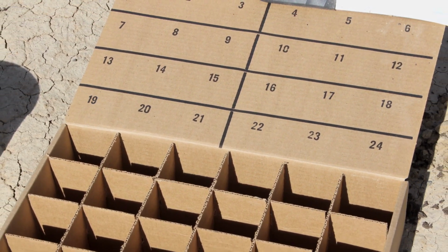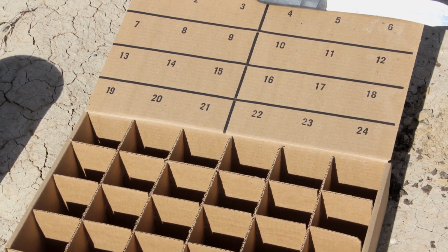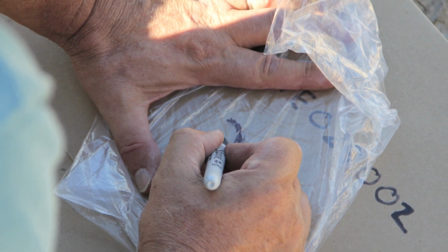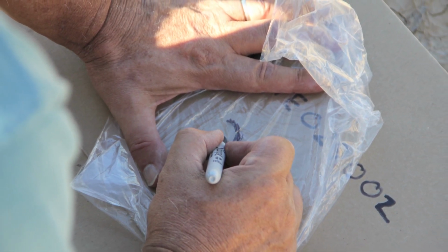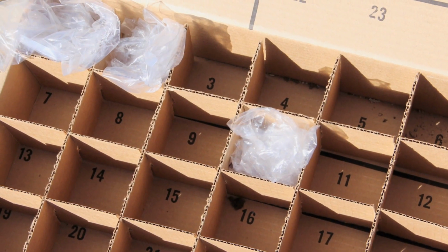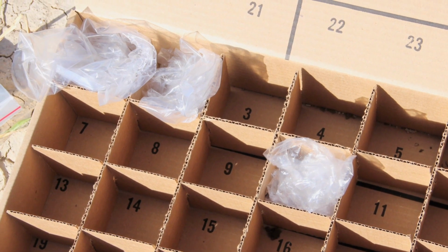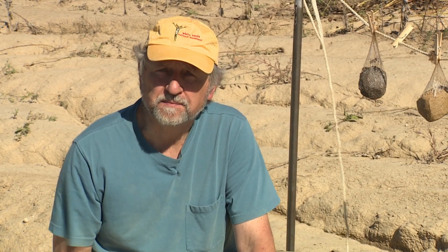The bags should be numbered with a sequential number of the samples that have been collected along that trip. The previous sample was collected elsewhere, so this is sample number 2. The clod is simply gently placed inside the appropriate bag, snugged up and tied off with a twist tie, and put in the appropriate cell. It's critical to get the proper data and number identification on the box and on the clod bag so that they can be matched up back in the laboratory. If that's not done properly, you've just wasted your time and you will get no data.